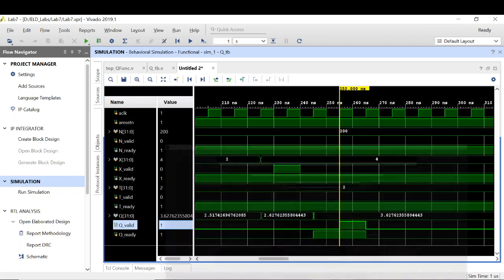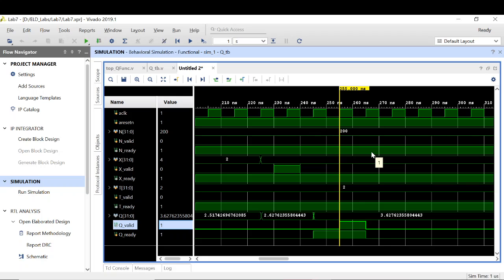Right, so in this lab, we learned about AXI stream. We are using the AXI stream protocol because there is no address phase. There is no storing of data. The data is streaming from master to slave. Secondly, we looked into the use of floating point IP and how to use different operations for our purpose. And then we looked into the valid ready handshake. So that's all for lab 7. We have done all 3 parts, and we have looked into all the aspects of AXI stream and this valid ready handshake.